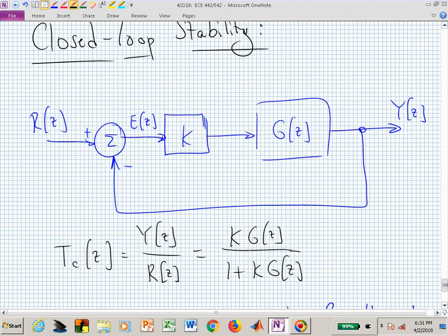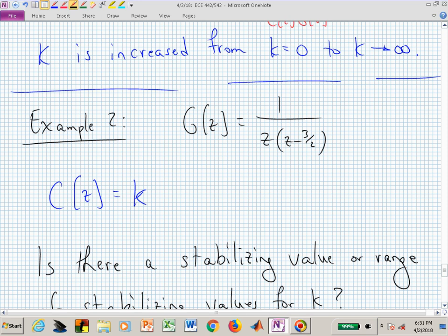How many open loop poles did we have? How many open loop poles do we have? And it doesn't take too many hands to show me the answer. If you give me 2 hands, that's okay as long as you don't show me any, or just 1 digit on each hand, right? So there's 2 open loop poles. How many closed loop poles? What's my controller structure? Did I add any poles with my controller? No, so I actually now just have 2 closed loop poles.